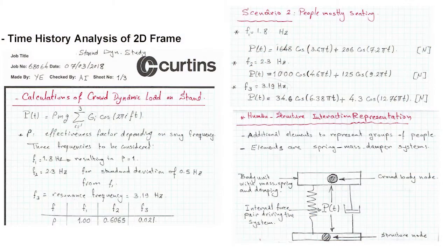Most of the existing structures have a frequency of about 3.5 Hz, which requires going through the complex method of analysis, which is applying the actual load as periodic loads to the structure, and then assessing the maximum response of the building, and then comparing that with the acceptable limits from previous experience.